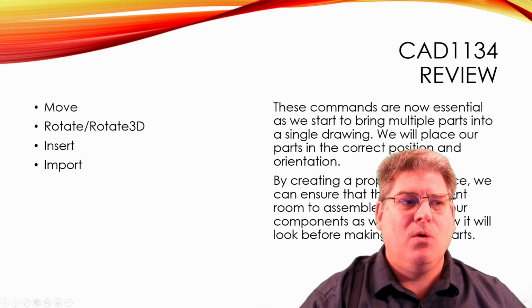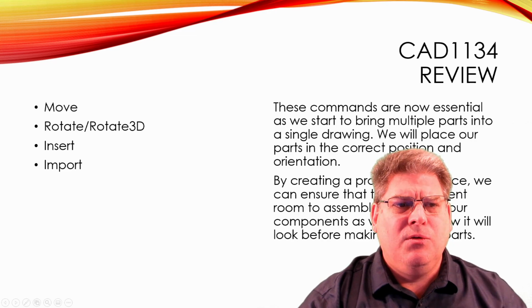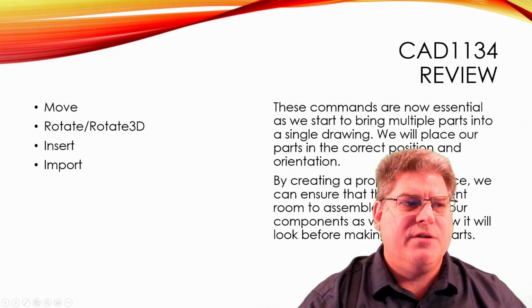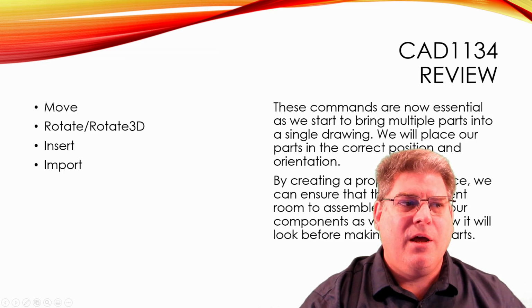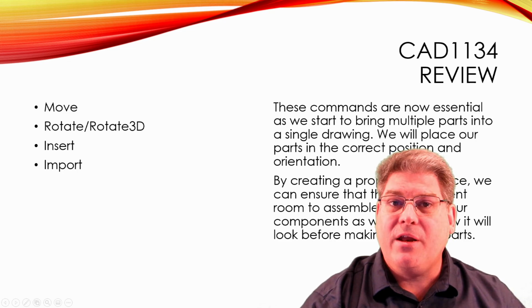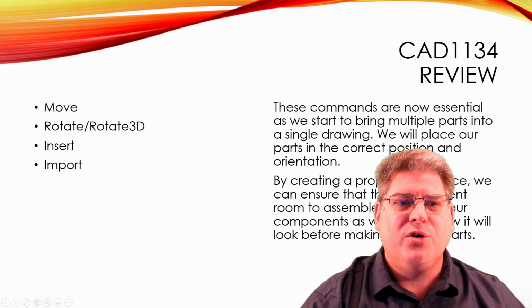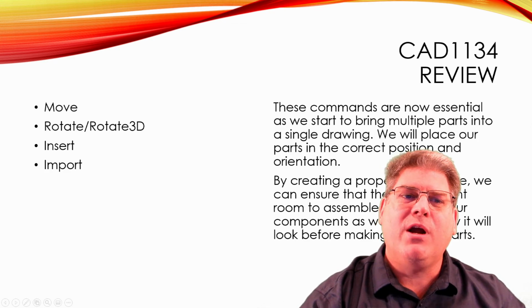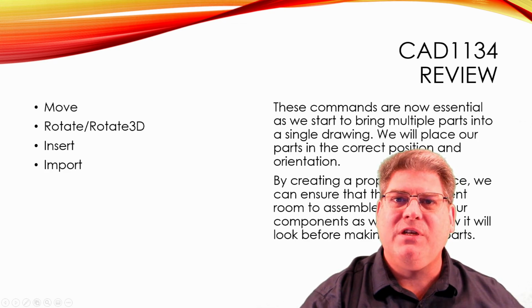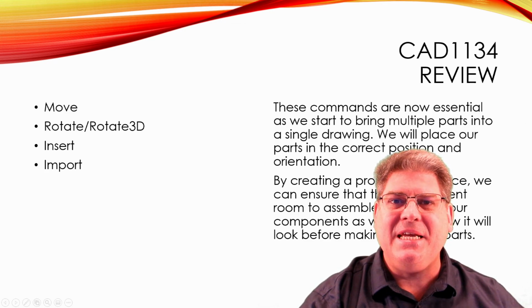Okay, so as far as the review, some commands that you should absolutely be aware of and familiar with are move, rotate, and rotate 3D, insert, and import. If you're not comfortable with these, I recommend you go back to the previous week and get a little bit of practice, because you're going to need it for this week's assignment.